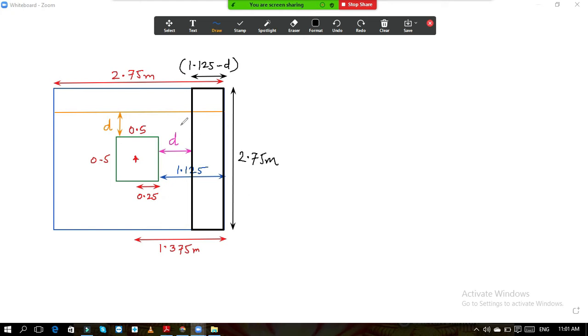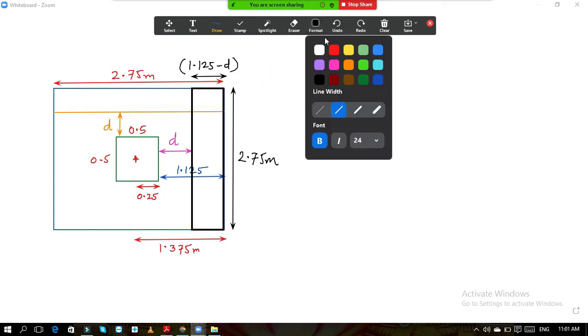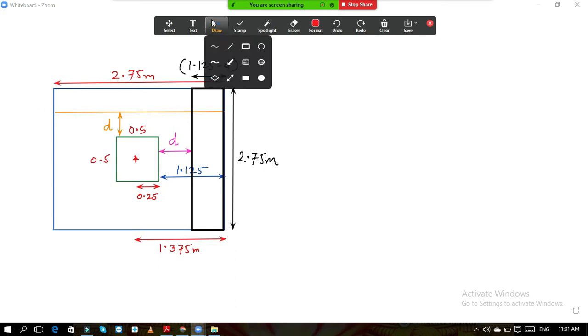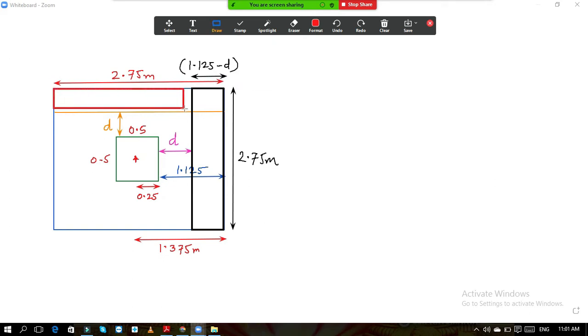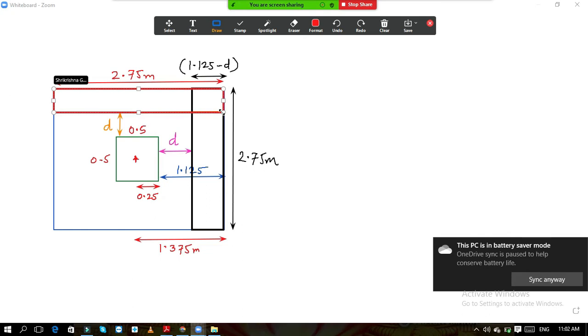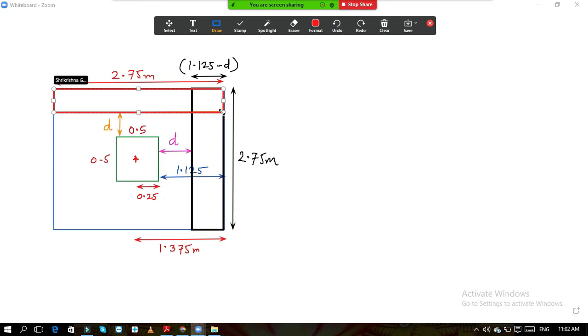So similarly on this side also, now we will consider the same strip along this y-axis. So here, if you consider this now, you will come across the same distances as we have provided square footing and square column. If the footing is rectangular, now note the important point. If the footing is rectangular, then you should go for the strip which is having maximum area.